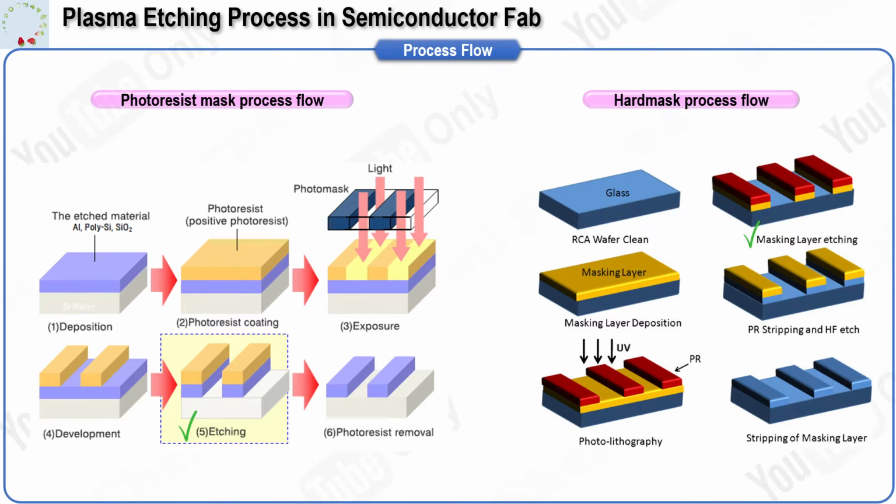The objective of plasma etching process is precise pattern transfer with tight control of critical dimensions and sidewall profile. The photoresist route is straightforward. Deposit the target film, coat and bake the resist, expose and develop to form the relief image, etch the target film through the openings, then remove the resist and clean the surface.